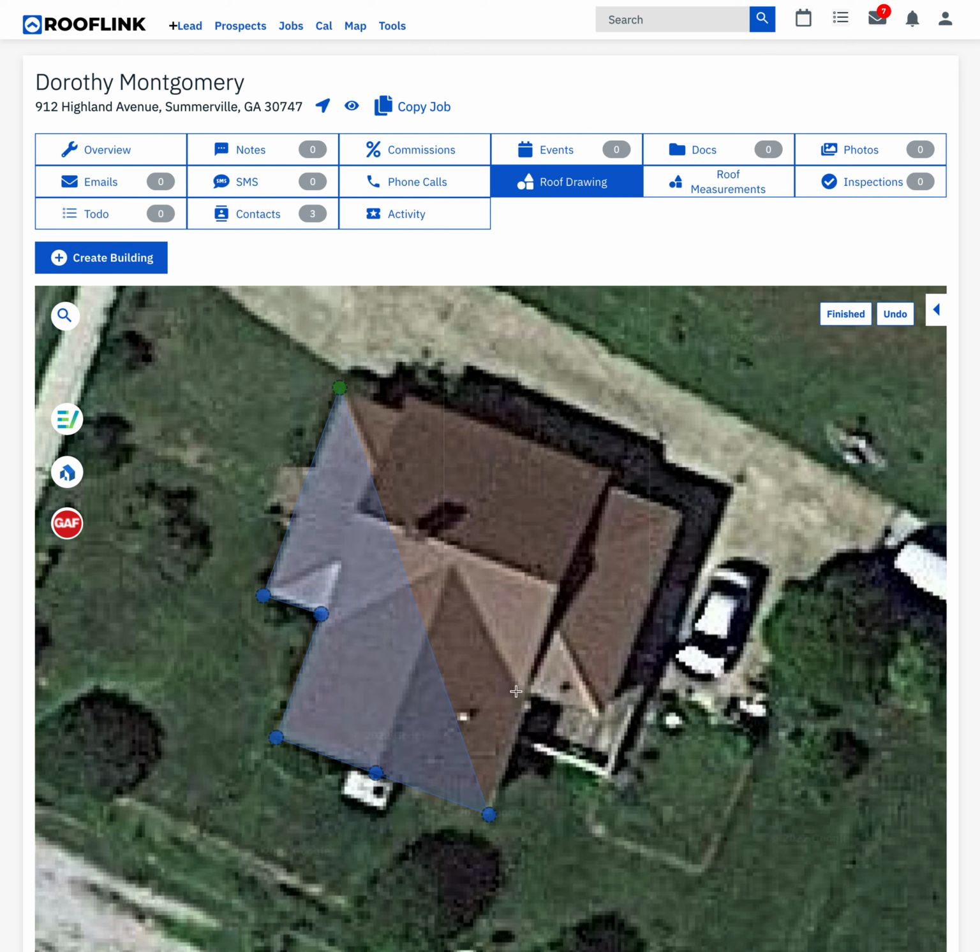It's going to automatically preset back to eave. So you'll click right inside this line here, and that's going to be an eave. That's already correct. You're going to click right outside your hip there, also an eave. Our next dot is going to be right here. Sometimes you have to do the dot in a different location and drag it because of the way the software is, but you could put the dot out here on the next one and then pull it back to where it actually goes. And so then we're going to come to this other corner.